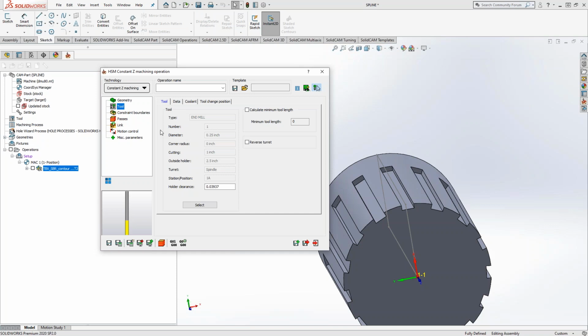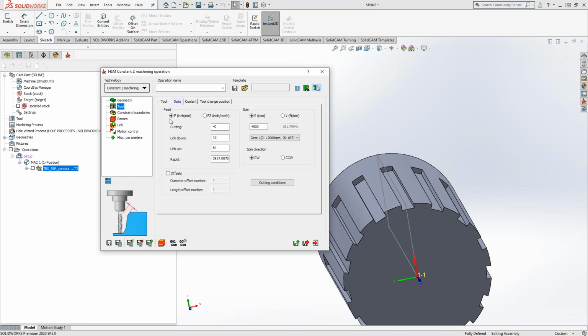But outside all that, let's say you just wanted the ability to, on the fly, on the controller, very similar to wear comp or diameter comp, just type in a new diameter for your tool. Well, every time you define a tool in an operation, you have this little section right here where you can check the box, and instead of defining just D1 and H1, you can define whatever size you want, change this number, and then in this one operation, this will output with a different call out in the G code.